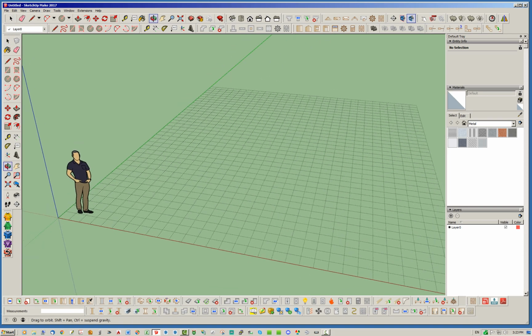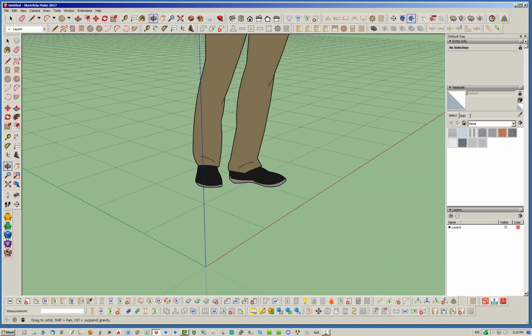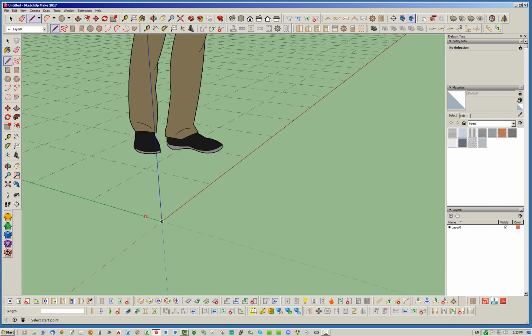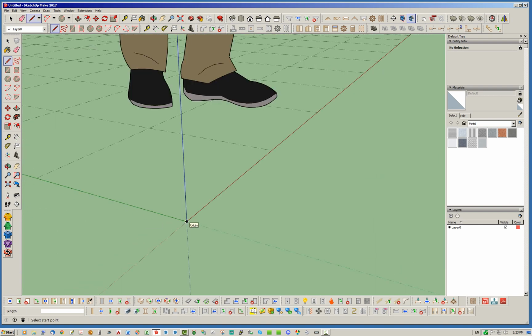Let's get started. I'm going to start by making what I call a 2x6 bottom plate. If I place this here, we can use a line tool, but it's probably just as easy to use the rectangle tool. Usually I'll key in my dimensions down here in the little box, and there you go. Then push pull that, of course.